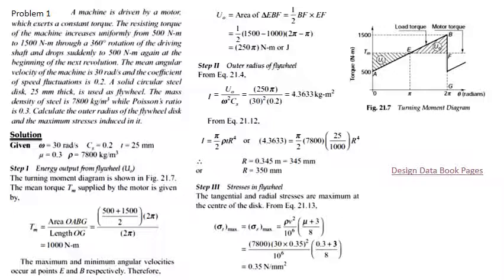So now we know that the mass moment of inertia of a flywheel for a solid disc flywheel, I, is equal to pi by 2 rho T R square. Now this formula is again given in the data book. So coming to the data book again, for the solid disc flywheel, this formula I equal to pi by 2 rho T R square is given in table 25.8 and equation 25.11.